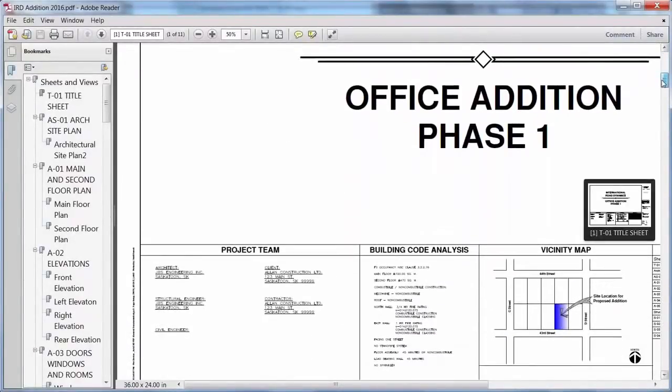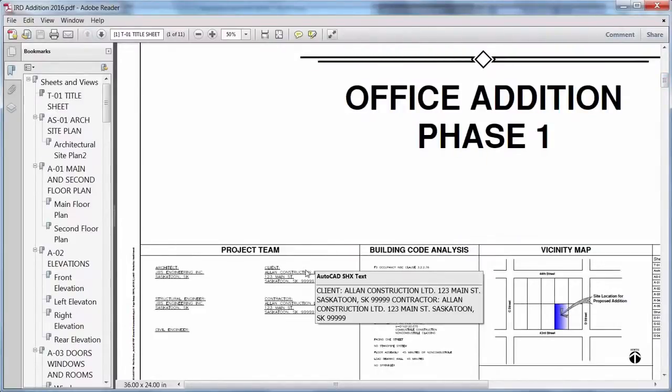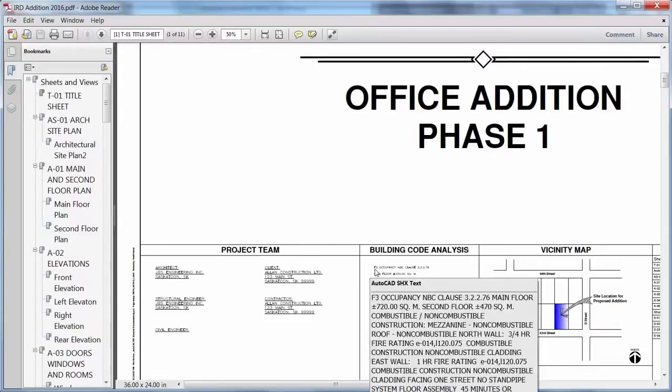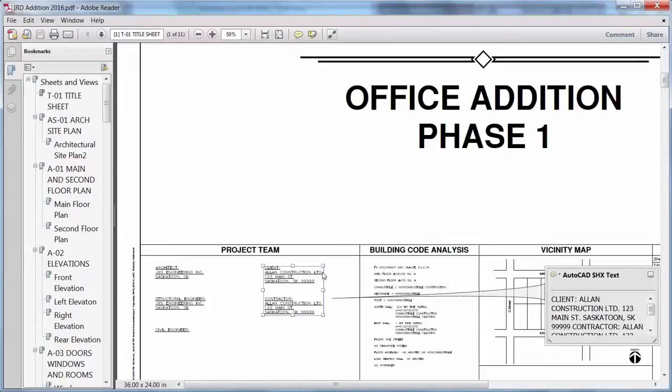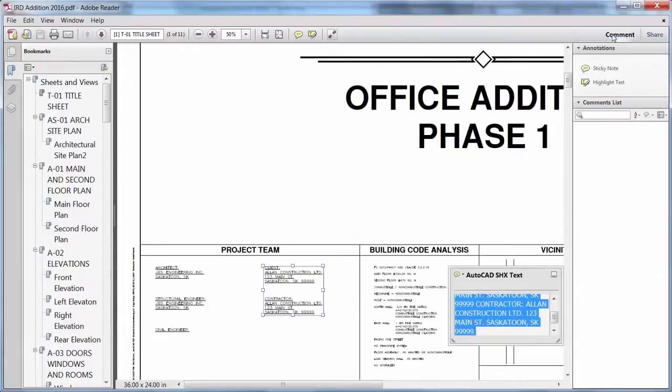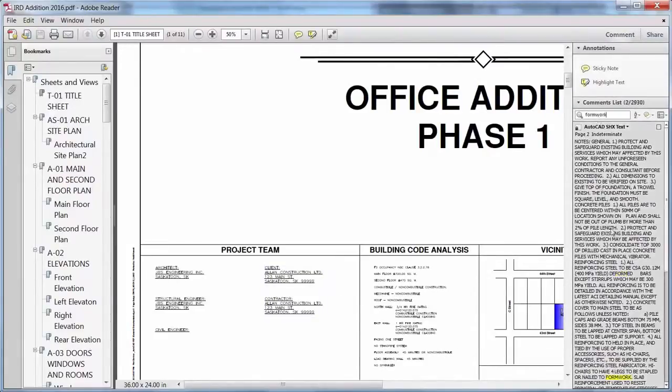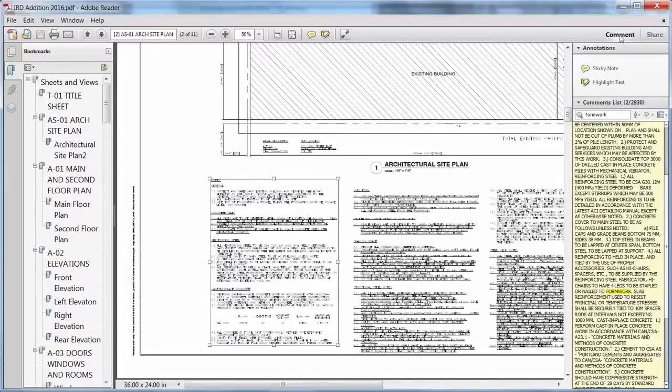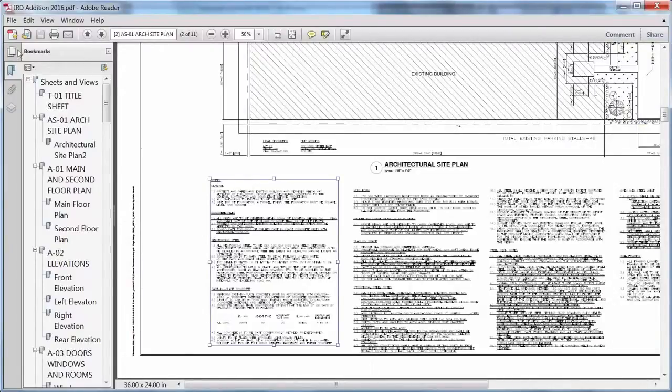Viewing these new PDF files in a PDF viewer also offers improved performance and additional benefits. Text created with TrueType fonts using any format options, as well as polygonized text and Unicode characters, are now searchable in PDF output files. Text that was created with SHX fonts in the AutoCAD drawing can be highlighted, copied, and searched as comments in the PDF viewer.